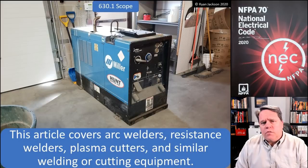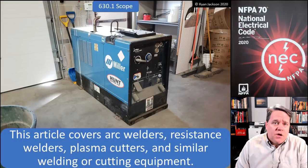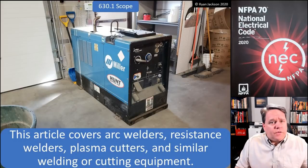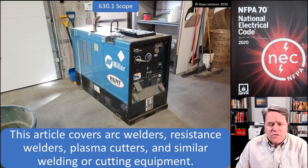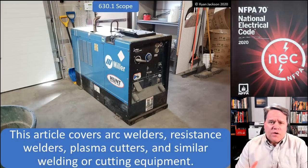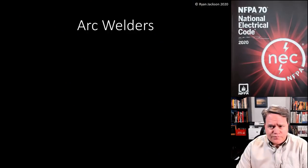So if you didn't read the scope, you might not know that a plasma cutter is considered a welder as far as the NEC is concerned. More specifically, it's an arc welder. So if we're doing a plasma cutter, then we would want to follow the arc welder requirements. So we have arc welders and resistance welders here in Article 630.